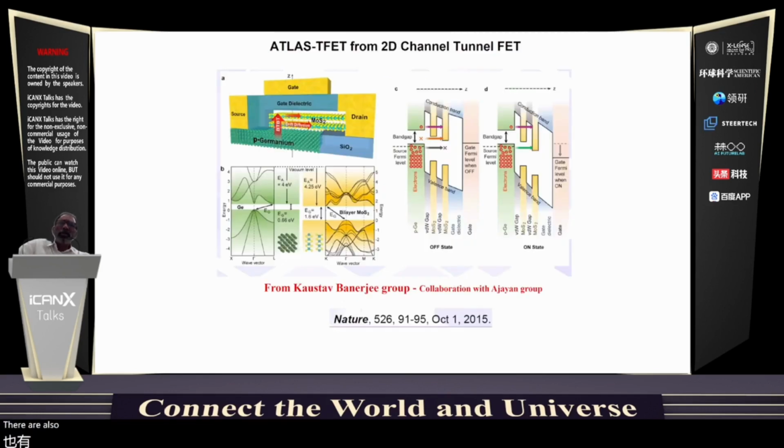And there are also some long-standing interest from the device perspective. Again, this is just an example of the work done from UCSB in collaboration with us on devising a new type of tunnel FETs. Again, as you scale down the size of the channel in semiconductor devices, you face lots of problems, electrostatics being one of them, or the swing, which is the thermodynamic limitation in how the voltage scales to the dimensions.